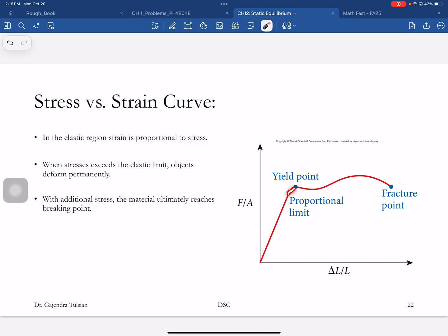Here you've gone out of the proportional limit region. This is the yield point. If you go beyond that point, the shape changes permanently. So for most materials, you'll have curves like this, and if you're making a living using these curves, you're making sure that you're using these materials in structures somewhere here. If you have driven over that bridge on 9A in Jacksonville, a beautiful suspension bridge, that's how you decide how many cables you throw in on that bridge. You want the stress to be somewhere there.